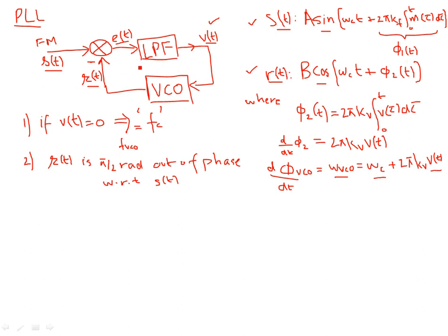Okay, so what we are interested in is a phase lock condition, which is to be achieved by the PLL. You can't have that if you cannot use a cosine. It will be a sine and a sine term, because sine will be in phase with sine. If you multiply sine and cosine, you will have sine of A plus B and sine of A minus B, and that sine of A minus B will be in phase with sine. So you need to have a pi by 2 radian phase difference.